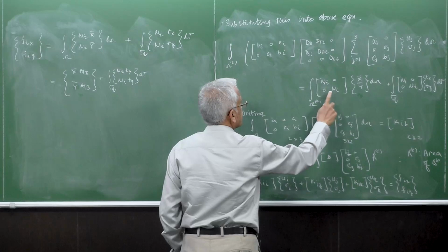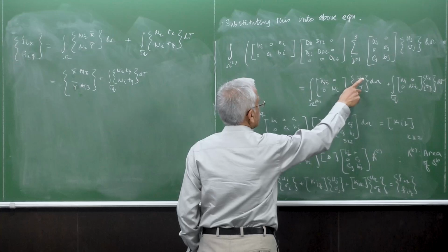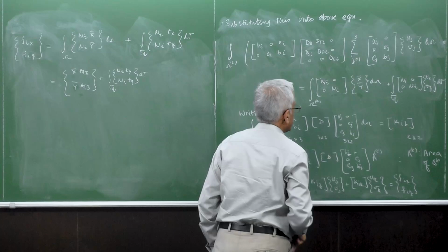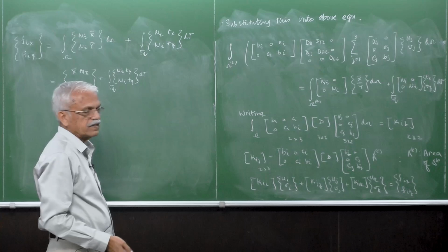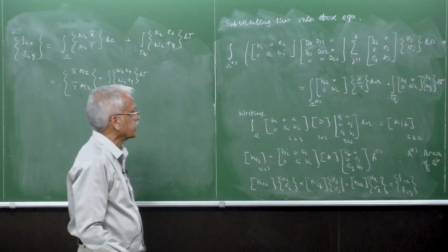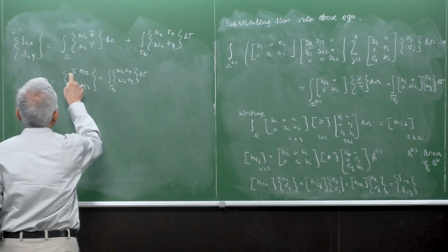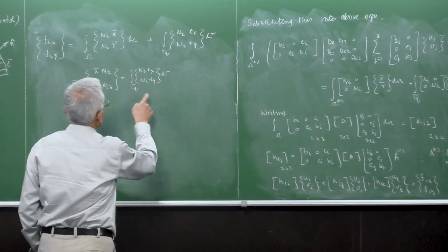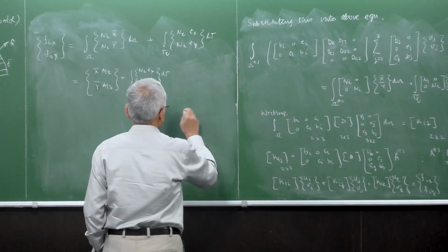integral evaluation of Ni on the body forces. So we know that it is Ni x bar, and the second component is Ni y bar. So if you integrate it, then Ni integral over the area will become area over 3, and that's what we have written. And here, of course, we are assuming that these body forces x and y are constant over the element. That leaves you now just another small component here.